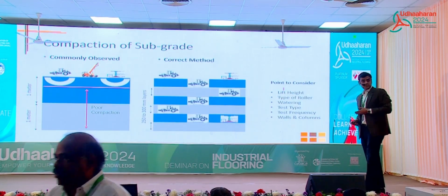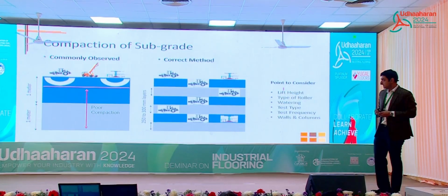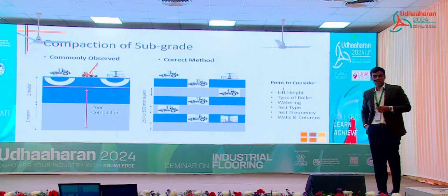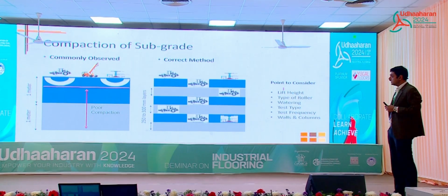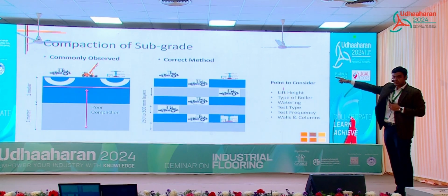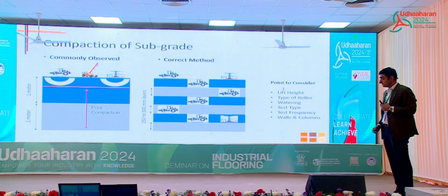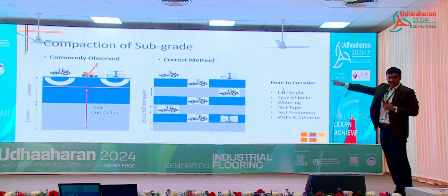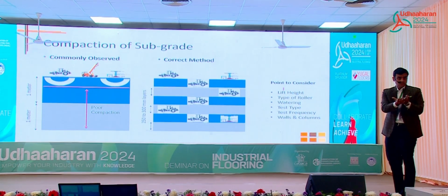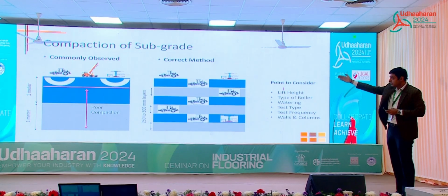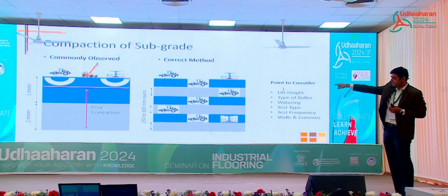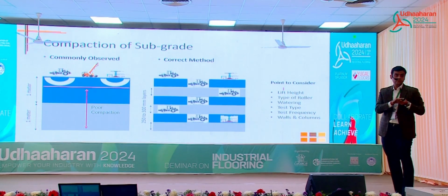Okay, a very important slide. How should we go about compacting? So what you see on the right side is what is fairly common. You kind of dump soil in lifts of about 1 meter. The first image I've shown is a roller, a vibro or a static roller. The white semicircle that you see is actually the bulb of influence. That is where your roller is able to exert any sort of influence. Below that, below the red line, it is actually not able to compact. So all the stuff below the red line is prone to settlement.